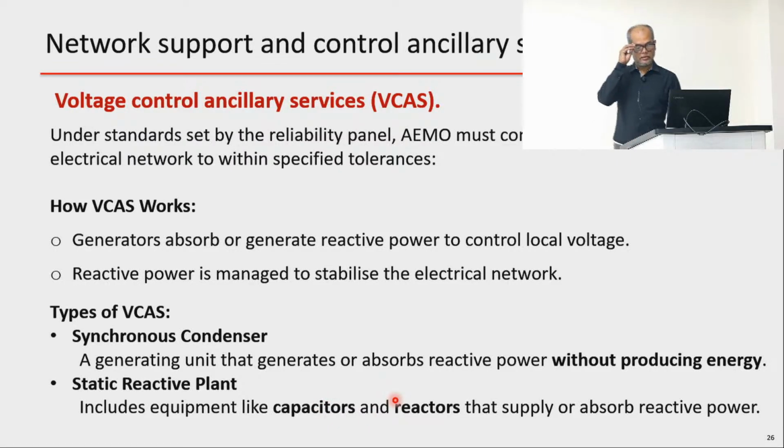The capacitor can supply reactive power, and the inductor can absorb reactive power. So most of the cases when you are talking about FACTS devices, it's nothing but the combination of power electronics plus capacitor and inductor.